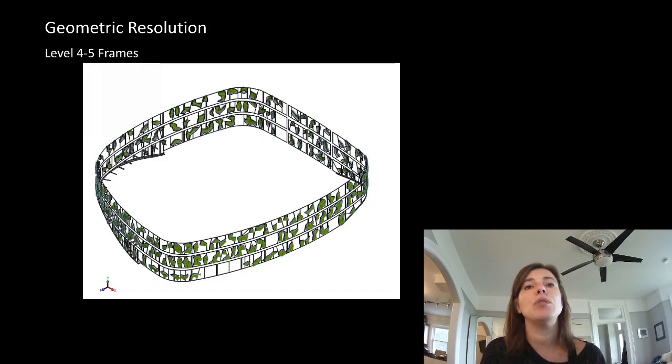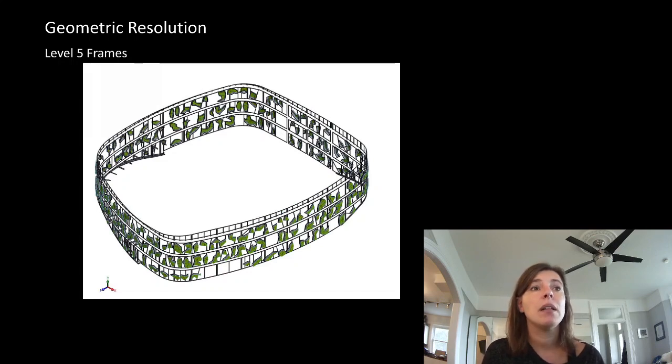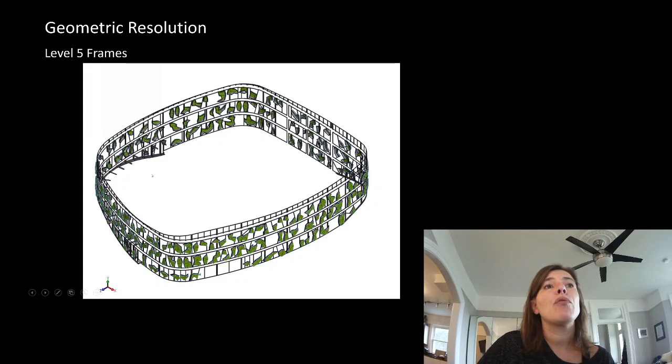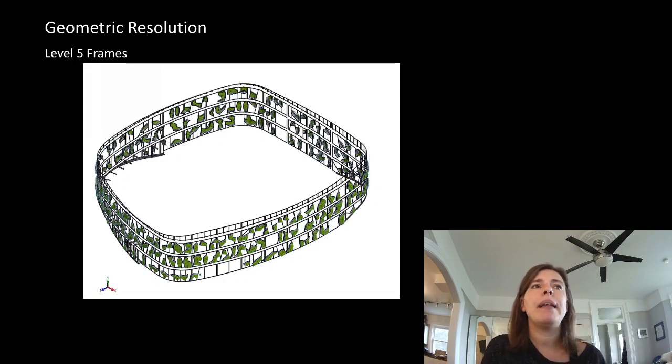So they asked me, would you do the parapet conditions as well? So I said, sure. And for those we actually did, because there was the ability to hide things a little bit more, and there were no windows in it, we were willing to weld, and the loads weren't that high, weld these down to cast-in tabs that we moment connected to, but we had a lot of tolerance because they just made the cast-in tabs bigger than we needed.